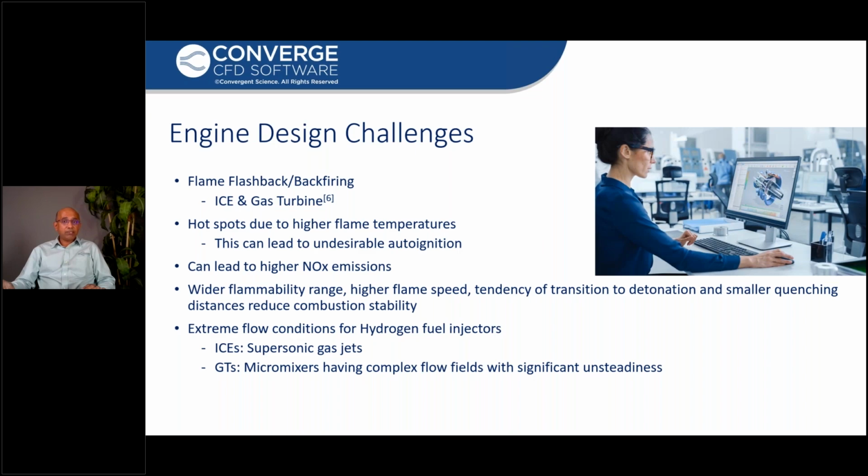Hydrogen trapped in cylinder crevices can ignite during the valve overlap period, which poses a flame flashback risk into the intake port in dual fuel engines, where a low reactivity fuel is mixed with intake air. Flame arresting devices should be installed in the intake port to alleviate these risks.